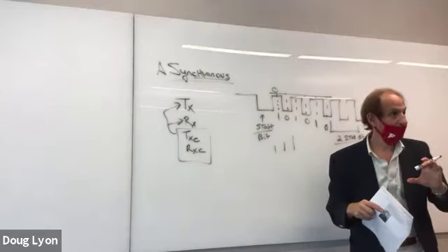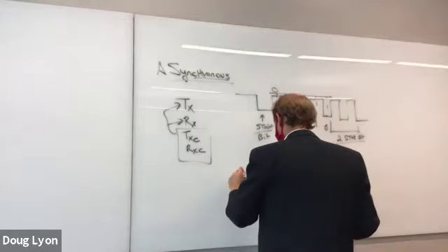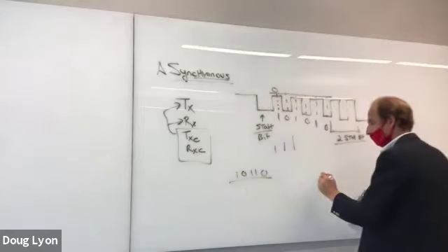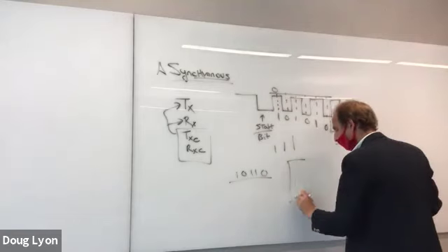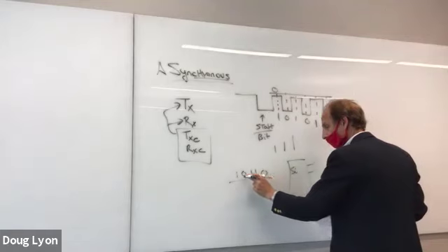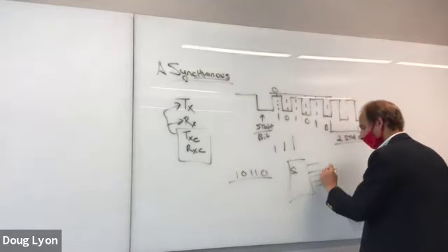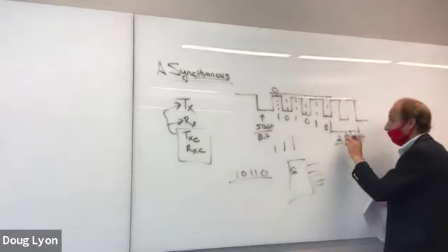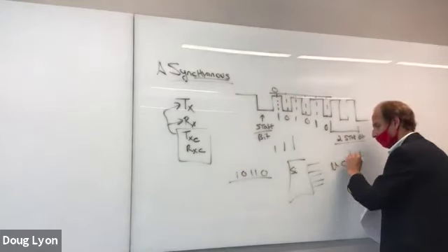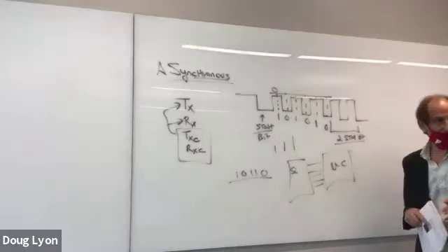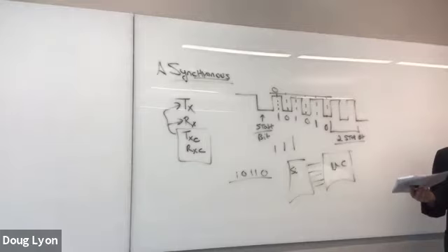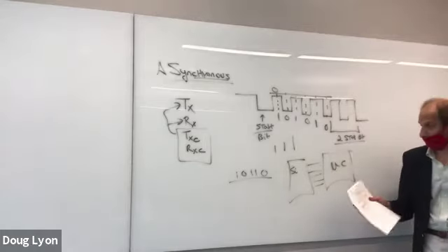to the computer. So if I give you 1, 0, 1, 1, 0 in sequence, what I want to do is go into a shift register with a shift input and then output 1, 2, 3, 4, 5 bits. And when they're done, and I'm about to hit the stop bits, I want the microcontroller to grab those bits and put them into a register which gets stored in memory somewhere. Perhaps you're sending strings off to your computer from your serial port.